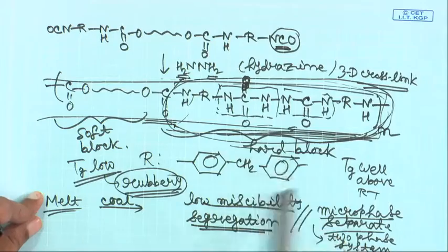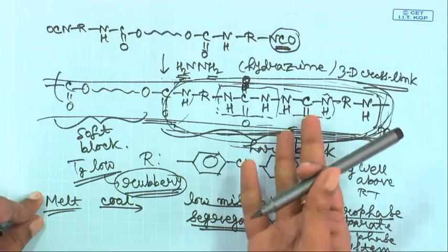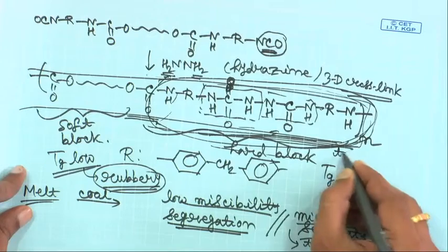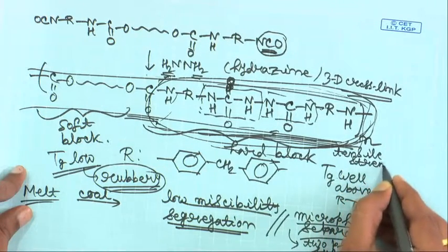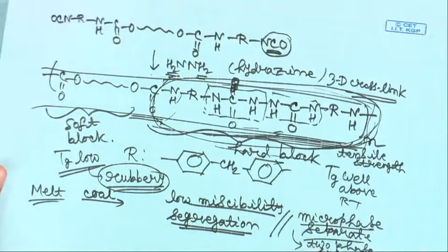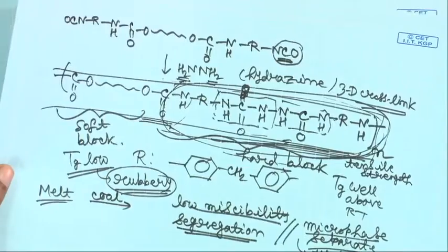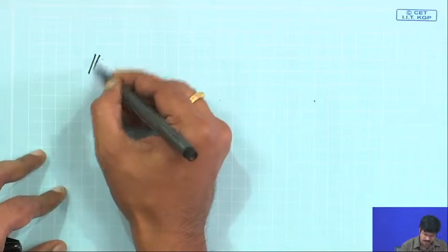Cross-linking is because of the hydrogen bonding interactions, all right. And the domains formed by the hard segments will be responsible for the tensile strength of the material and for the stiffness of the material, all right. So, if you look at the situation a little bit more closely, what will happen when you cool the system down? You have these kind of domains that will appear.